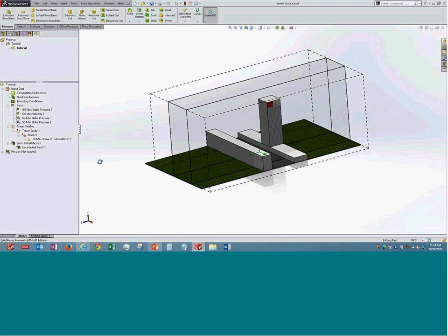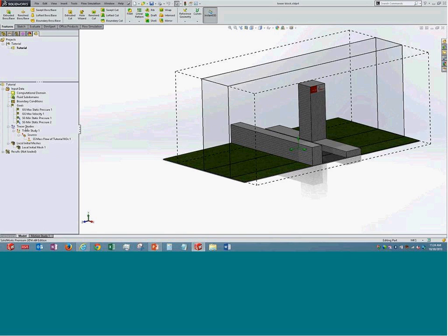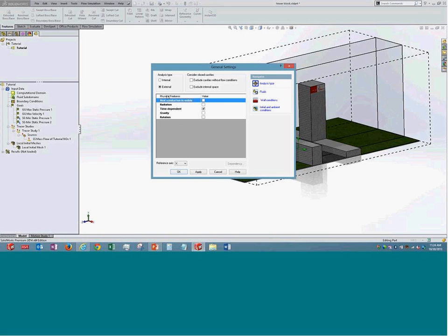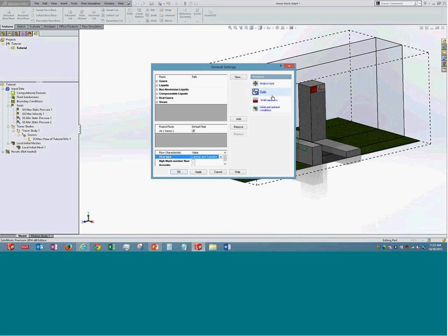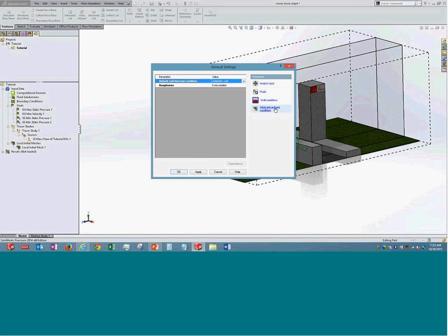That is, at a certain height the velocity will be different, and it goes on changing as we go down the system. So to simulate that scenario, we are giving an equation here, and that has been given as a global condition. So if at all it is an external analysis, then we can specify the inputs over here itself.